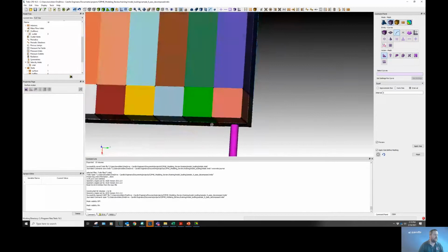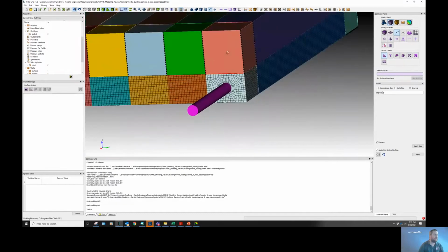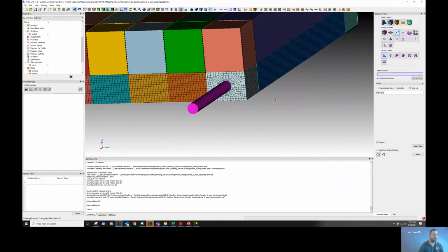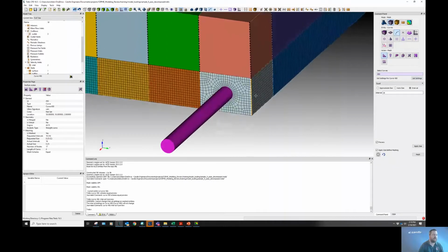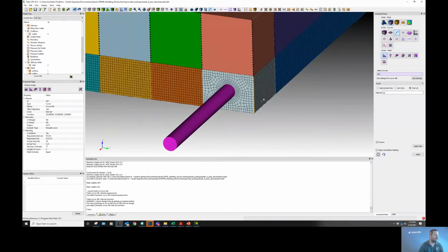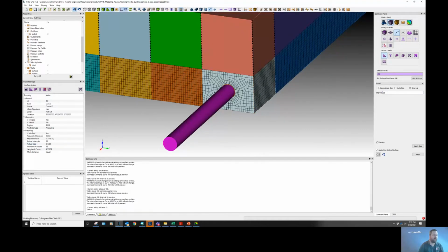I have initially defined some of these boundaries. So often we'll define it by the edge, or edge size, either number of intervals or element size. So on this edge, we've defined 16 intervals or elements with a size of 3 inches. On the wall of the pipe, we've defined 36 intervals around it, for a little over 2 inches for our size.